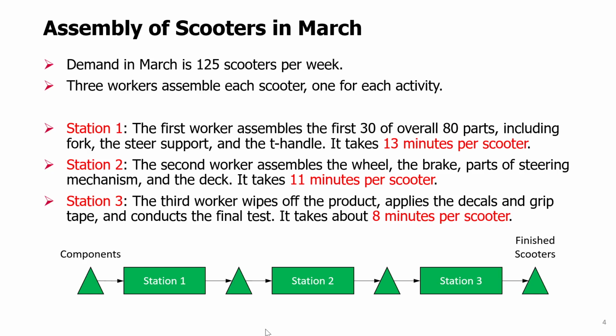They have a lot of activities to learn, and so the speed at which they learn is slower. So they don't become as efficient as they could become when they only learn a few activities each, right? In big assembly lines where, let's say, cars are made, you have a very large number of stations, and each worker does just a few parts or even attaches just one part, and then they learn much faster how to do their activity much better and become much faster at it, and also do a better job, probably from the perspective of quality.